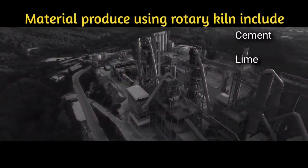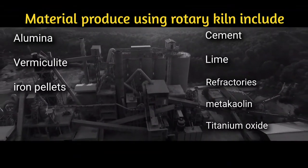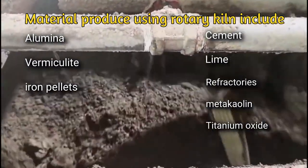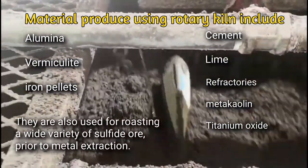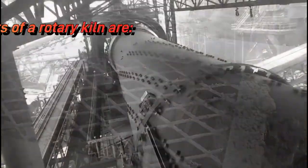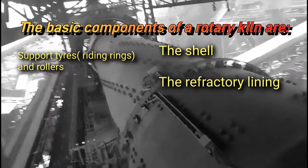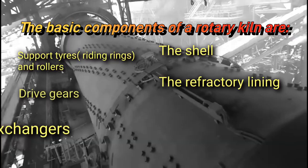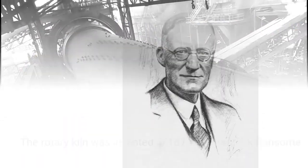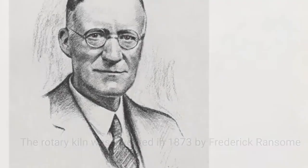Materials produced using rotary kilns include cement, lime, refractories, metakaolin, titanium oxide, alumina, vermiculite, and iron ore pellets. They are also used for roasting a wide variety of sulfide ores prior to metal extraction. The basic components of a rotary kiln are the shell, the refractory lining, support tires, riding rings and rollers, drive gears, and heat exchangers. The rotary kiln was invented in 1873 by Frederick Ransom.